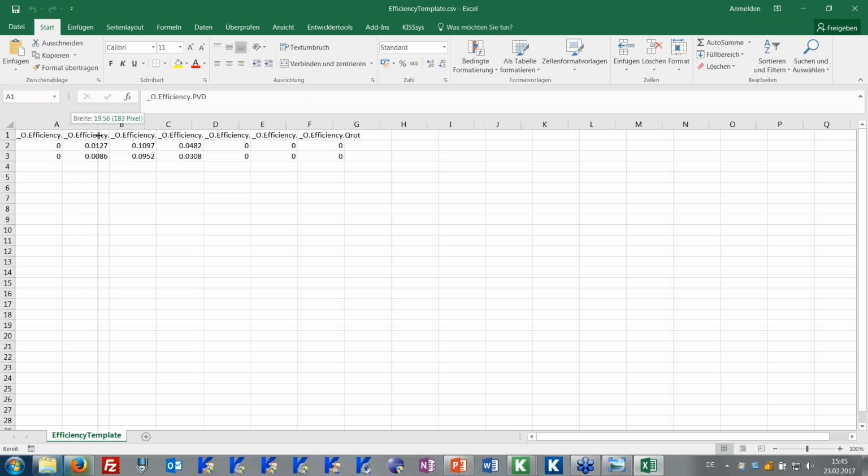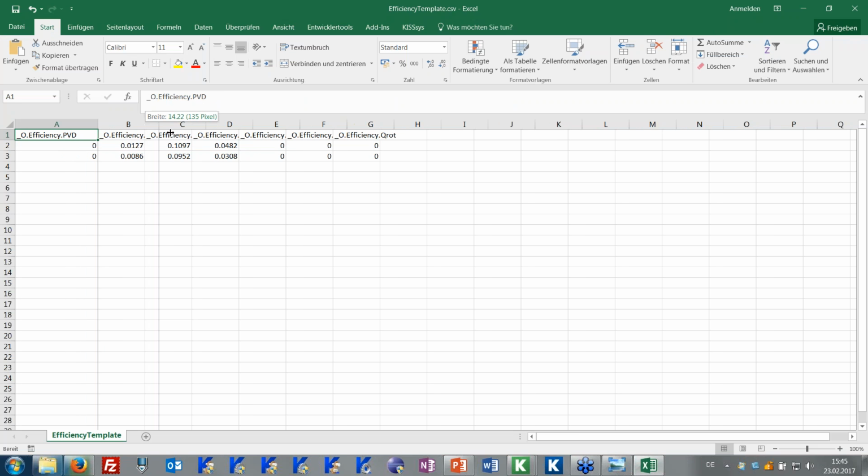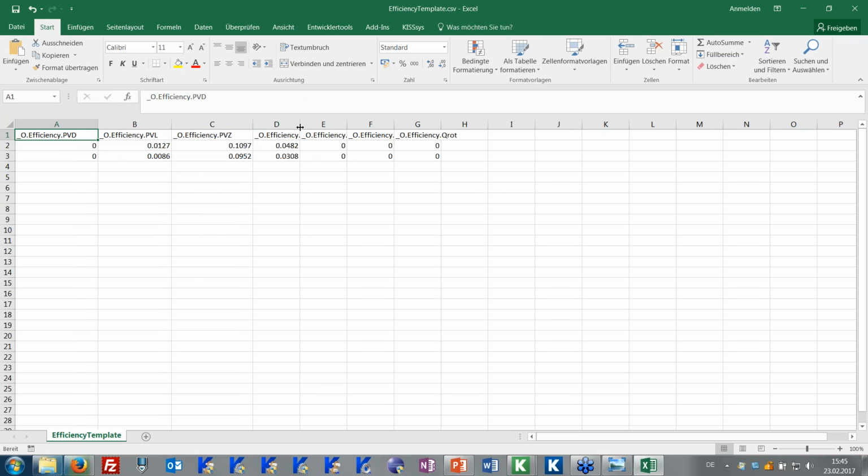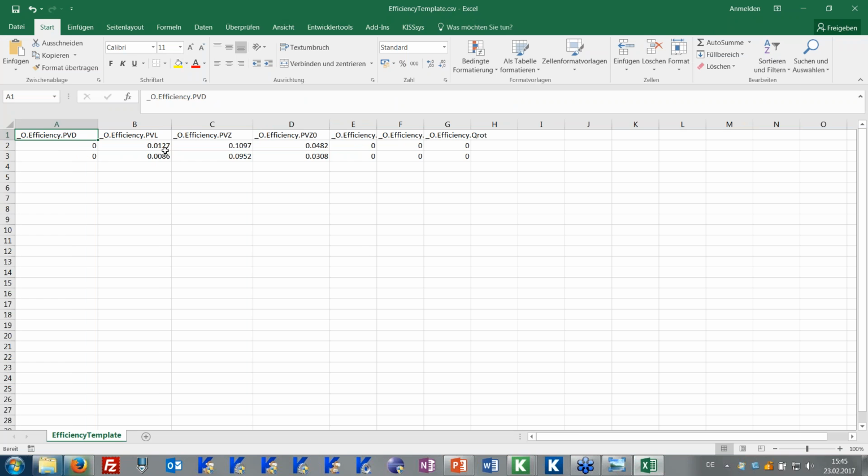and you will find for every bin the results here, the losses, as expected. So this is my prepared file, but normally it is written out like this. So I can see for bin 1 the losses for the gears and for the bearings. This is for the load dependent gear losses, and this is the non-load dependent losses for the gears.